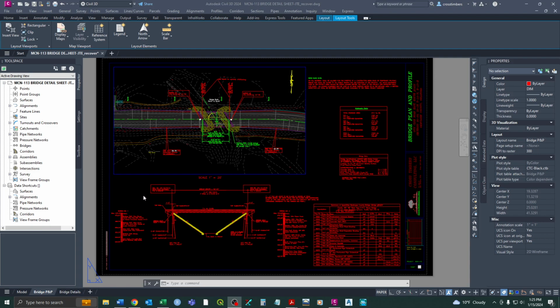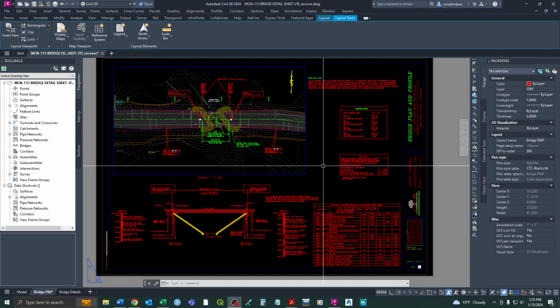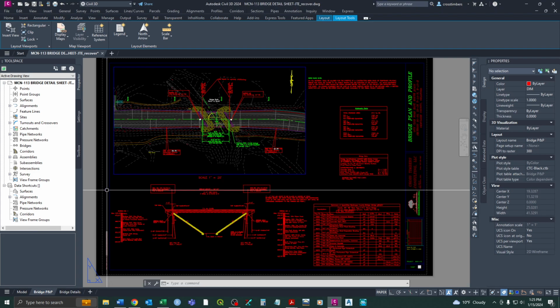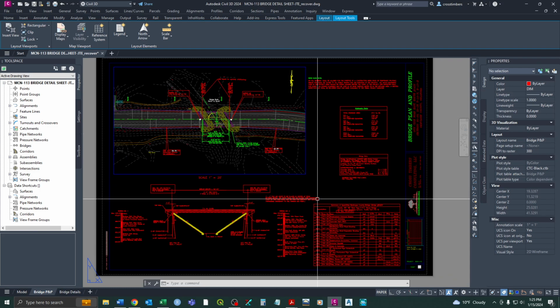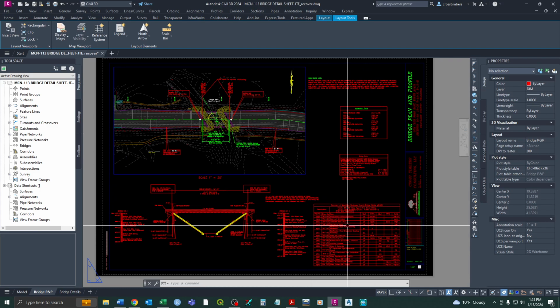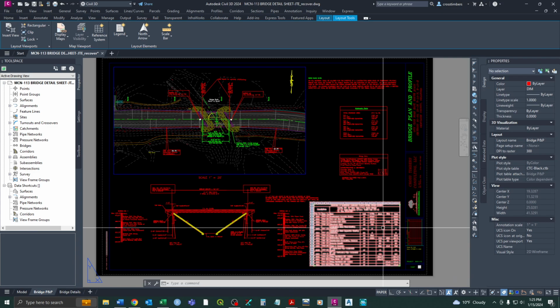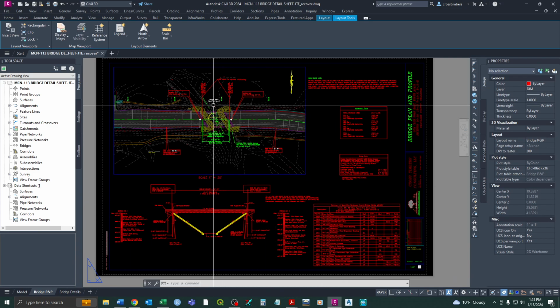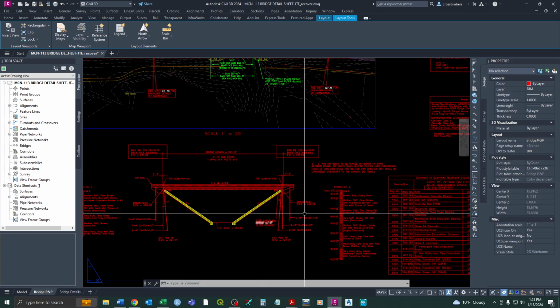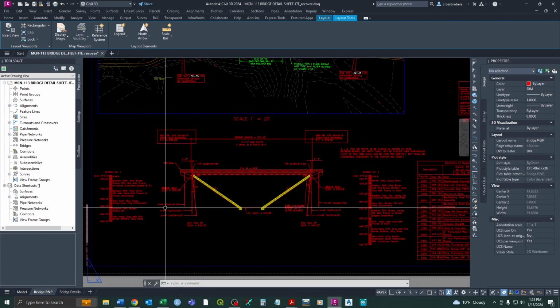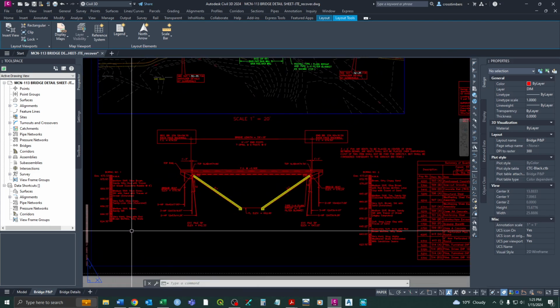We're going to be putting in a 55-foot type 2 PC beam bridge that's on a 30-degree skew to fit our creek channel. This is just the generic bridge sheet, plan and profile kind of sheet within our plans. But we include, here we have just the full overall quantities, but we try to give an idea of some of these other quantities as well in here, and some other features like the geotech report.